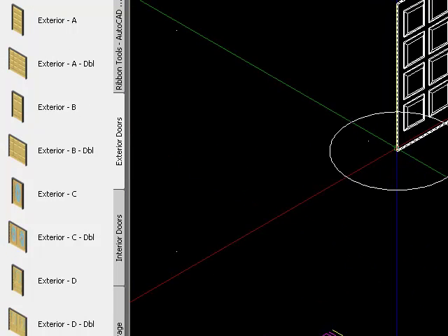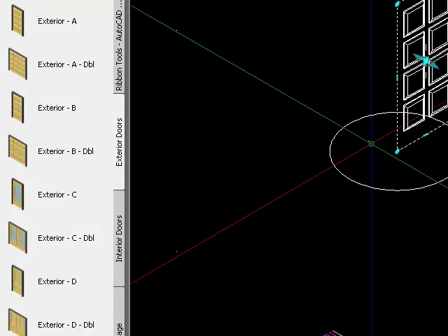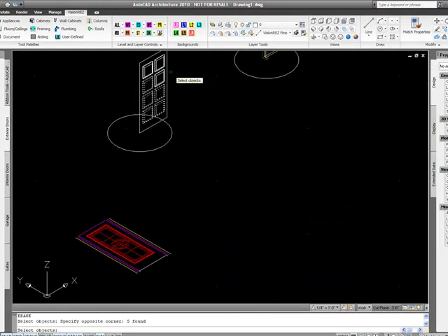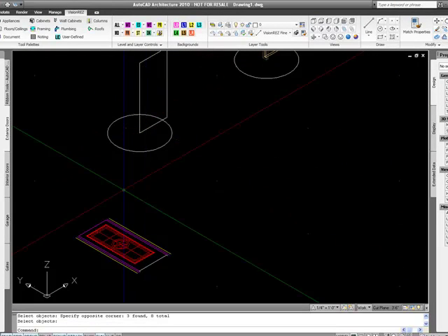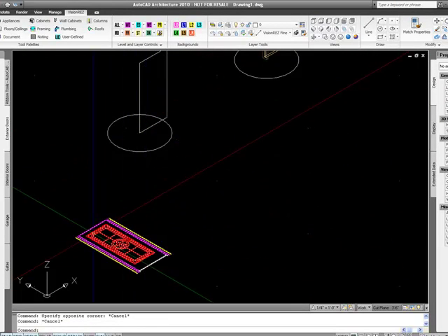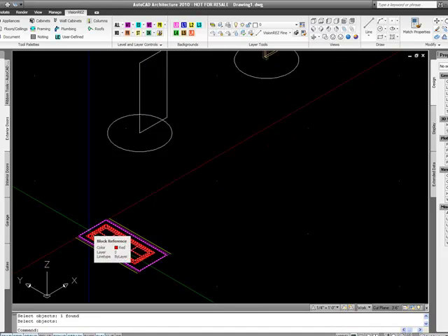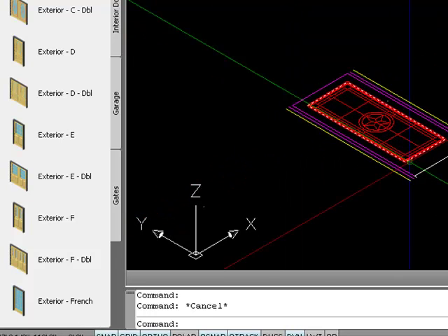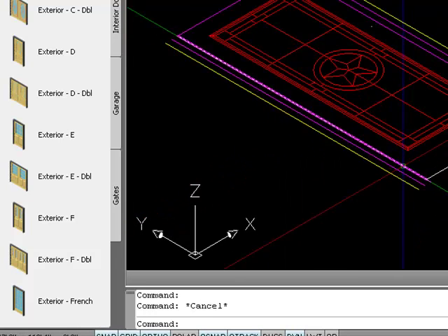I'm pretty satisfied with the exterior door shape. I'll just keep that mass element. The mass element that I do want to change though are the interior blocks here. So I'll go ahead and get rid of the default interior blocks. And what I want to do is explode this 2D block that they sent. This is the door that they're wanting. So now I've got that.